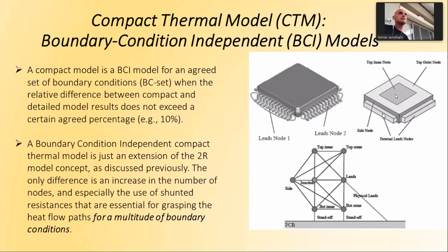Why would we? This is our chip. This is our proprietary data. So we derive something which is thermally equivalent to the detailed model, but is not the detailed model. It only has thermal resistances and nodes. Between two nodes there is a thermal resistance.